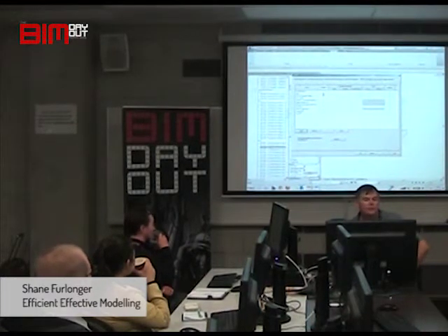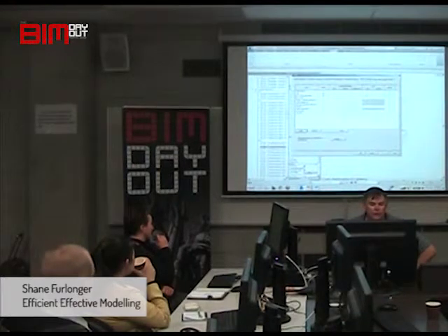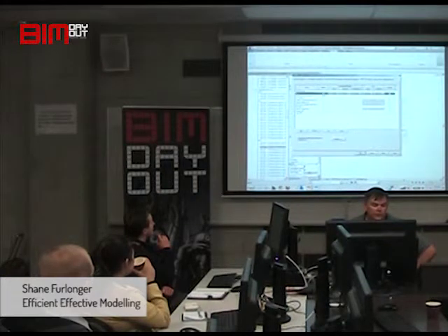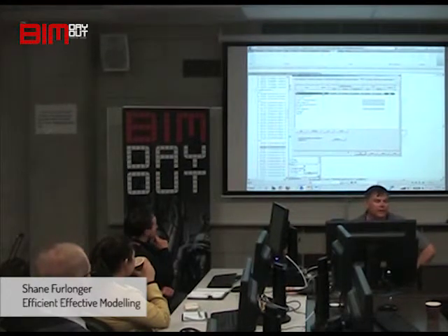So some things you may want to turn on, and you may want to change the way it looks. So you keep the tab ticked, and you go in here and change how you want that item to look. Or you can just turn it off completely, and then when you apply it, it'll turn that item off. So that would turn off all walls that have brick in the name. The one I just created. So that's how filters work.